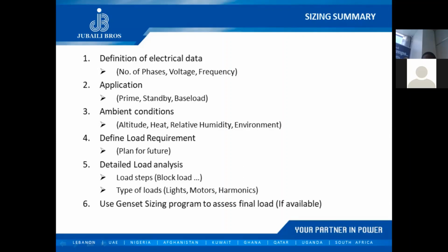We've talked about derating factors, typically altitude and ambient temperature. We've discussed planning for future expansion. We've also had a very nice example of load stepping when we discussed load shedding, and we also discussed different motor starters and their effect on starting current.